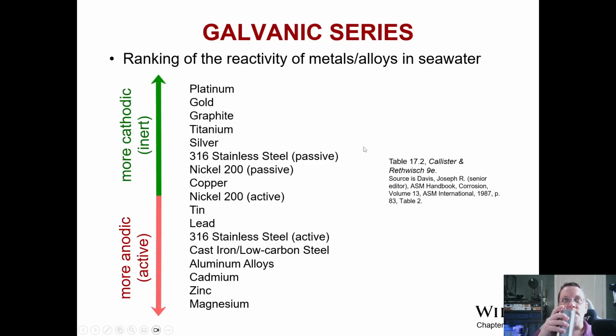There's also a galvanic series to understand what things are inherently more cathodic, so things that are less and less reactive as you go up the scale. Platinum sitting at the top, that's why we use it in a lot of electrodes. Gold is just a really great material overall. Not good structurally, but for a lot of applications where corrosion is present, it's one material that does a lot of things really well, especially in terms of electronics and some of the capabilities.